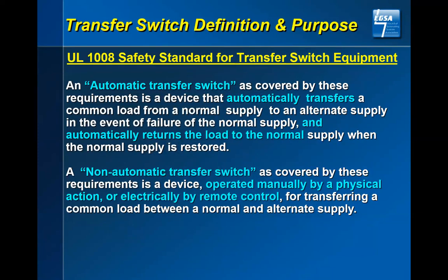Now, we look at UL 1008. You're going to see some references to UL. Transfer switches are manufactured under a set of NEMA or some type of manufacturing code. When you look at UL, you have to send your product to UL, Underwriters Laboratory, and explain to them how you are going to operate this safely. In the case of transfer switches, ASCO, Russelectric, Zenith, Cummins, Kohler, Generac, all of those typically fall under UL 1008. Therefore, they are a transfer switch for emergency systems.